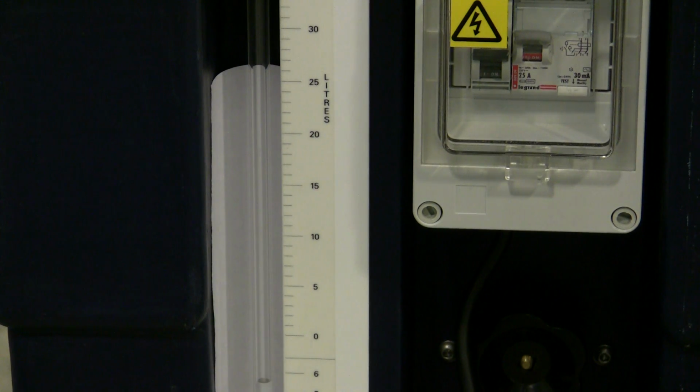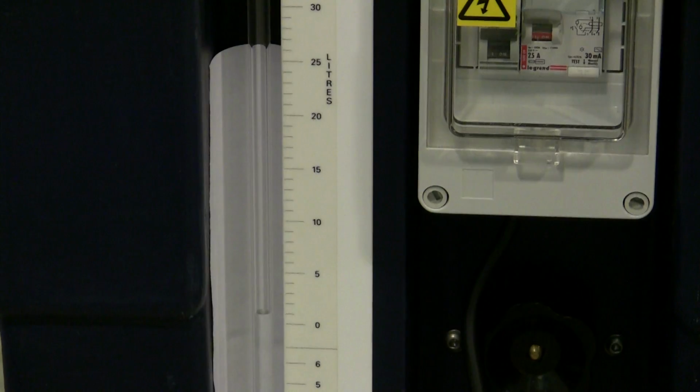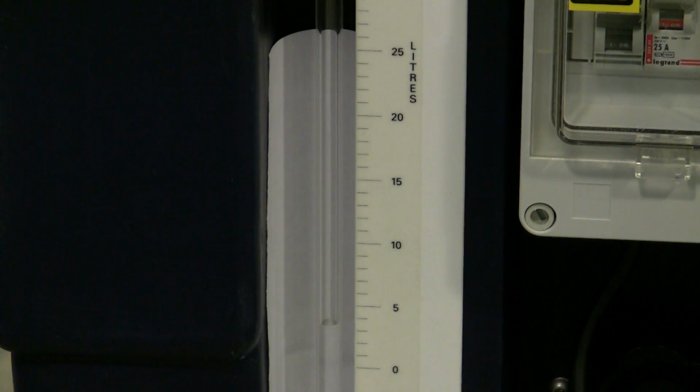Okay, so now we're going to quantify the flow rate for the second round, for the low flow rate. So you'll need to get your stopwatch at the ready for when it crosses the 0 mark. Zoom in just a bit to make the view a little bit better. Okay. And since the flow rate is lower, obviously it's going to take more time to accumulate the same volume of water, so maybe I won't wait for it to go all the way up to 25. We can get a nice accurate flow measurement for less flow.